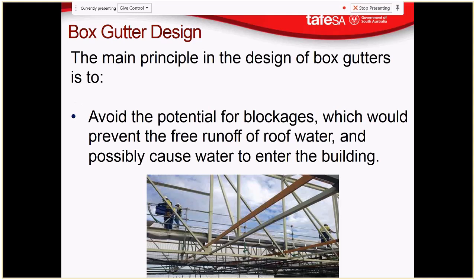And then you have a little bit of a lip in here, and you have a ball in there that will float, like a styrofoam ball or a hollow plastic ball, and then we have a little hole there, and it's best practice to run a pipe away from that tiny little hole at the base, and then your downpipe continues up there. So when you get water coming in here, the water initially goes down there. So that's your first flush.